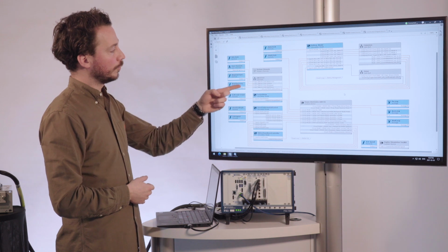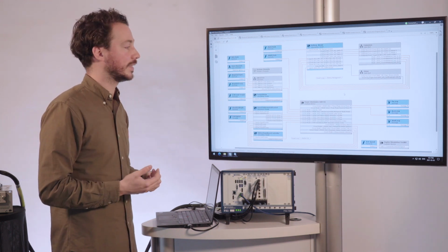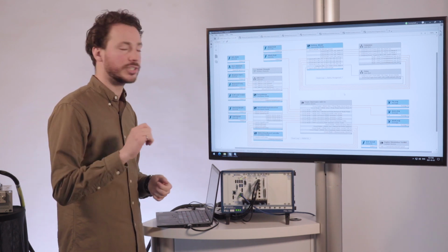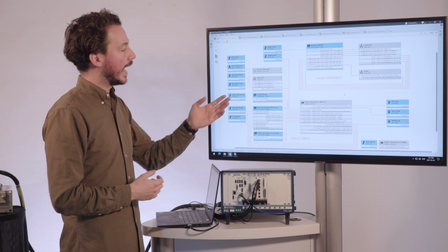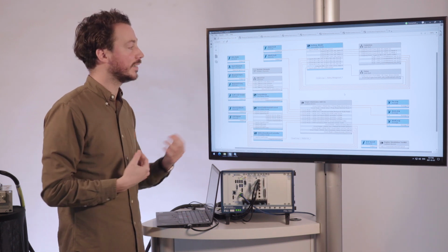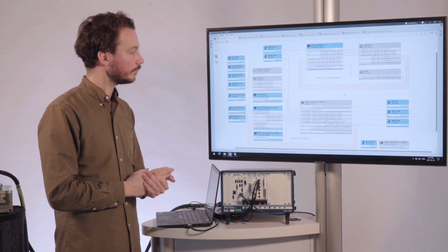So for example, we have the ECU. The Pi-Innovo device, right, that's the supervisory control. It has certain inputs like the battery state of charge, the ignition, etc. And all of this is going to be part of the decision power that it's going to need to either activate the combustion engine or the electric machine, etc.